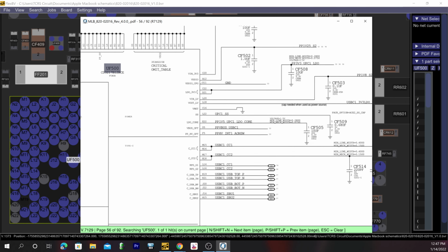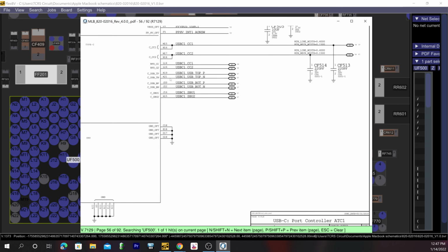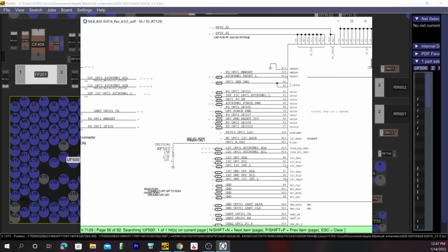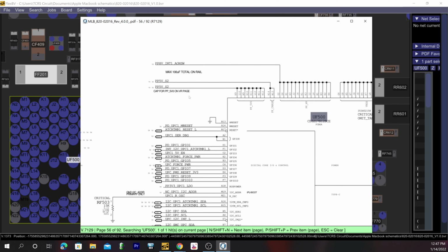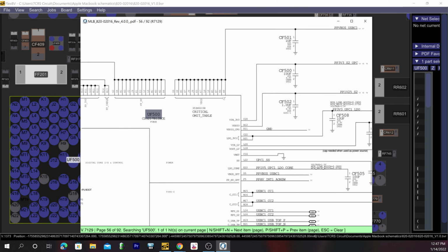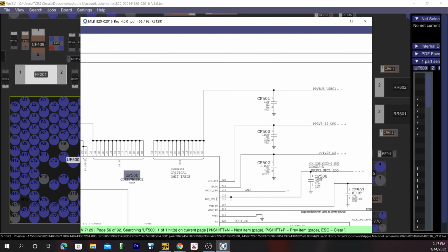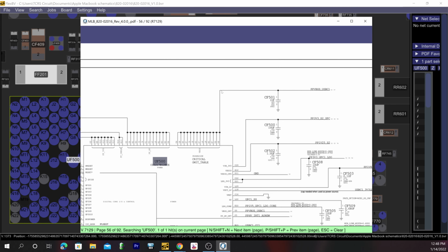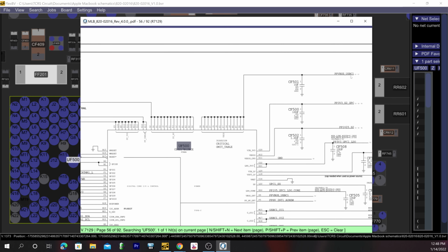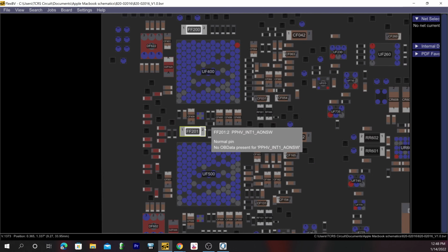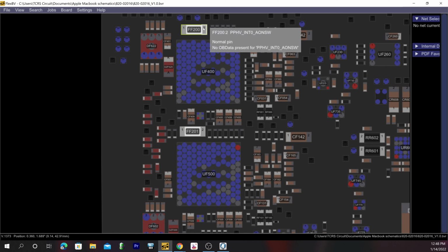In this case, the way they're doing this is a little bit more complicated compared to the CD3217s. Generally, if any of these rails are missing, either PP5VS2 or PP3V3S2, then that can cause issues. Let's just go over how these rails are generated, so I understand before I'm writing. So we have PPV bus USB-C 1, and let's figure out where this comes from.